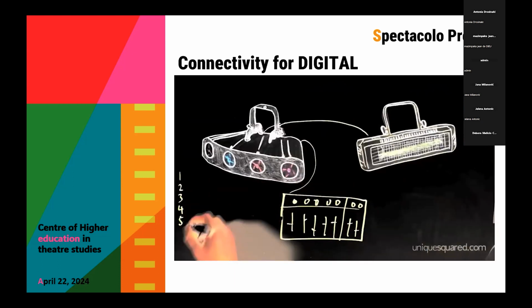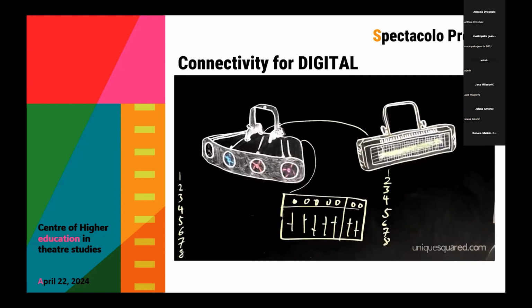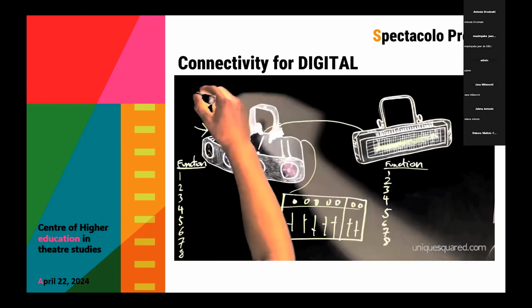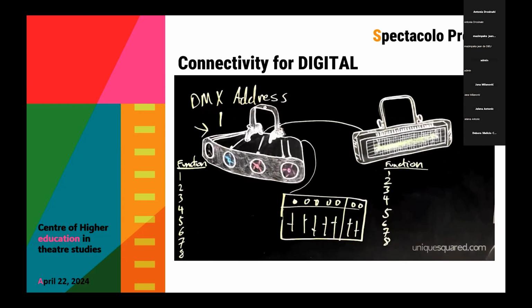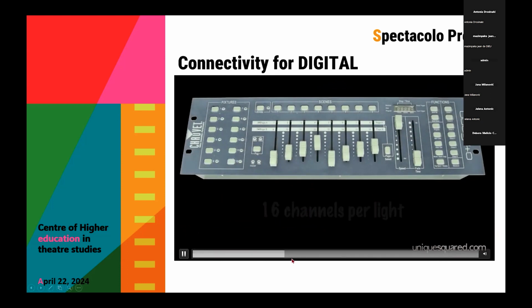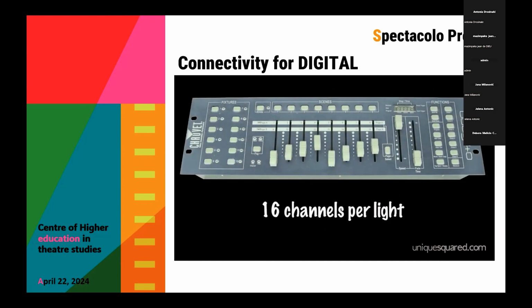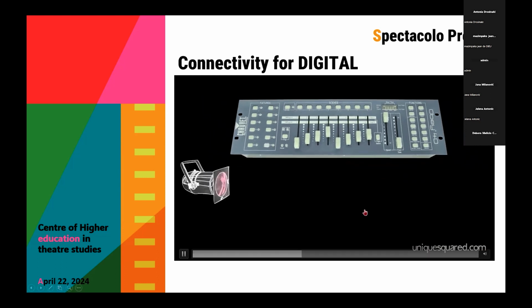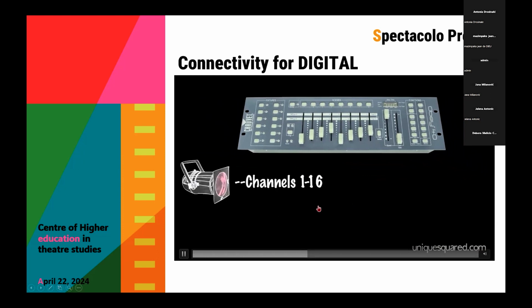Now, remember from part 2 how we set our DMX address. The first light starts with the DMX address 1. For every single one of those 12 lights, my Chauvet 40 has 16 dedicated channels of control. That means the first light gets channels 1 through 16.